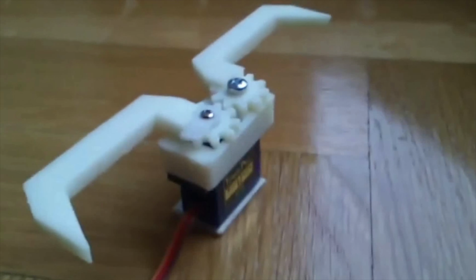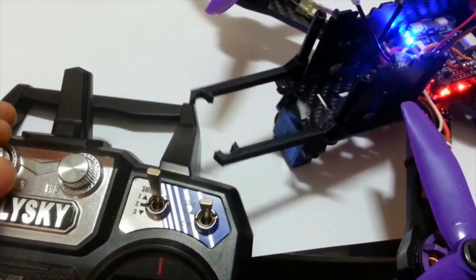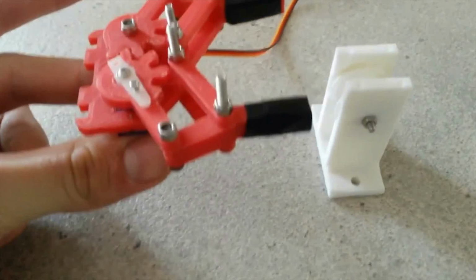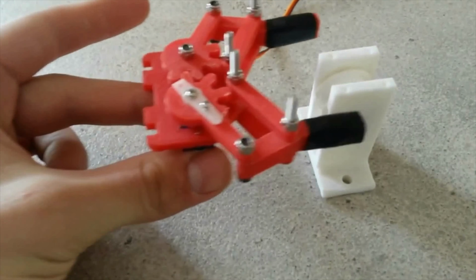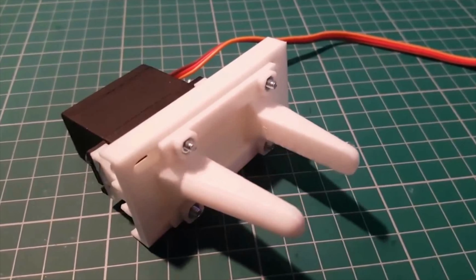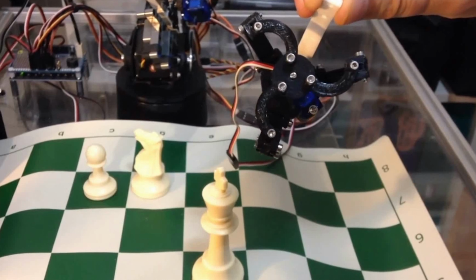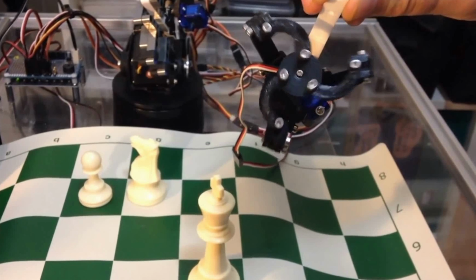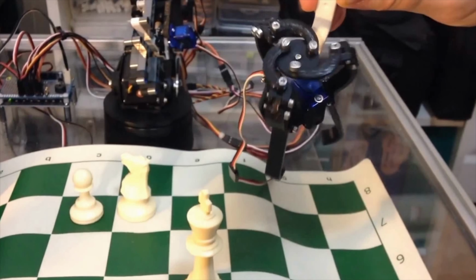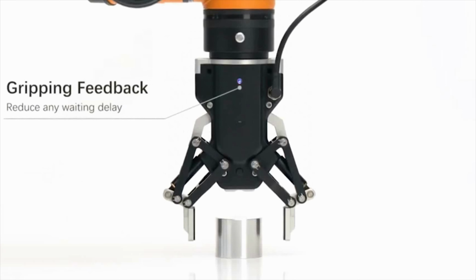The shape of the finger's gripping surface can be chosen according to the shape of the objects to be manipulated. For example, if a robot is designed to lift a round object, the gripper surface shape can be a concave impression of it to make the grip efficient. For a square shape, the surface can be a plane. Though there are numerous forces acting over the body that has been lifted by a robotic arm, the main force is the frictional force. The gripping surface can be made of a soft material with a high coefficient of friction so that the surface of the object is not damaged.